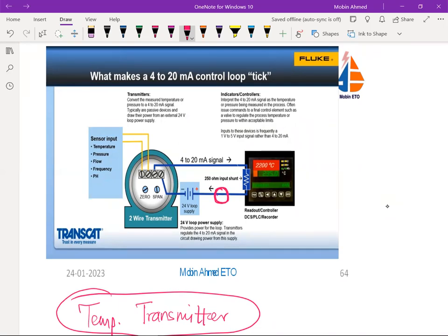And I am going to put in a milliampere meter, which means a multimeter set to milliampere current. Remember, the multimeter should be in series with the circuit. Only then can you check the current.